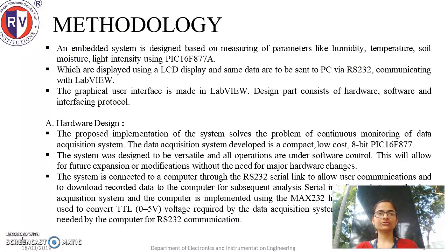Coming to the methodology of designing this project, an embedded system is designed based on the measuring parameters like humidity, temperature, soil moisture, light intensity using a microcontroller named PIC16F877A, and those data are displayed using an LCD which is connected to the microcontroller through RS-232 communicating with LabVIEW. The graphical user interface is made in LabVIEW software. Designing part consists of a hardware and software implementation and interfacing protocol.